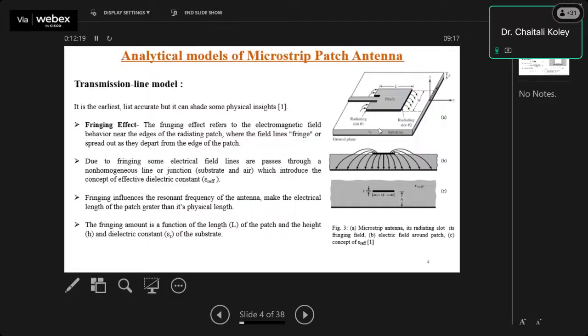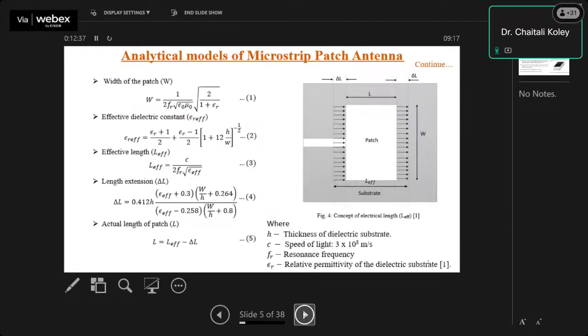So this is basically one kind of equivalent circuit of the cavity resonator. Whenever we consider a coaxial probe, there should be one inductor in series, and then the parallel RLC should be there. So these are the basics.